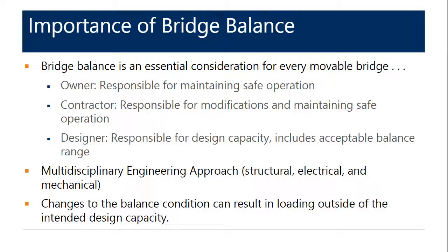Consideration for movable bridge balance requires a multidisciplinary approach among structural, electrical, and mechanical engineering. Changes to the balance condition can result in loading outside of the intended design capacity. We were involved in a project where the balance of the movable bridge was changed to meet the requirements of the rehabilitation design. However, with the span balance altered, within the project constraints, the driver was unable to operate the span. The balance condition had to be changed to ensure safe span operation.